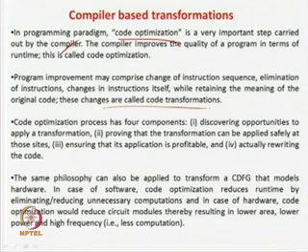What are transformations in this case? You are transforming code A to code B by doing some optimization or doing some redundant elimination, etc. But you should be very careful that whenever you are doing the transformation, there should not be any change in functionality of the code, because you are doing only optimization, you are not debugging. You are only trying to improve performance, so that the code is executed in an optimized way, or your hardware requirement is less in case of VLSI, but the input output behavior should remain the same.